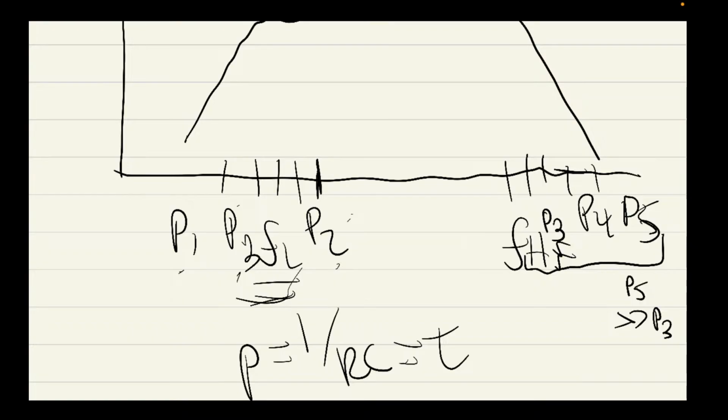So all of these poles are approximated by adding them up in series. And then the lower bound of FH is taken by taking these higher poles and adding them in parallel. Does that make sense? And so these poles, if you go back to what I said earlier, these poles are your coupling ones, your low frequency ones, and these are your high frequency ones, your shunting ones.